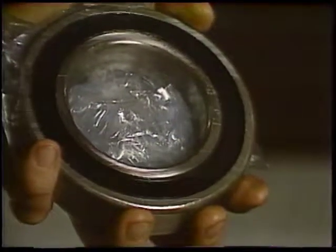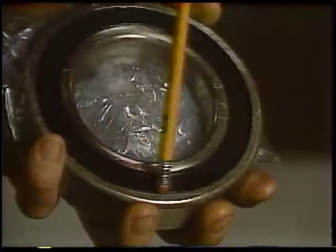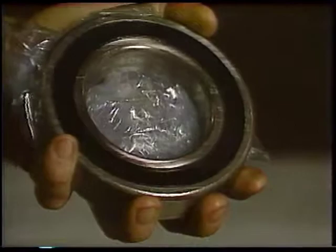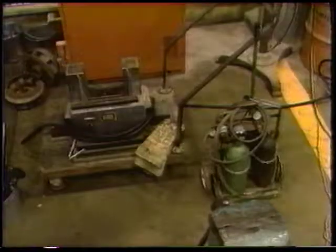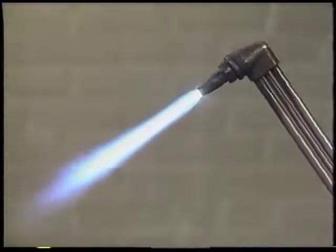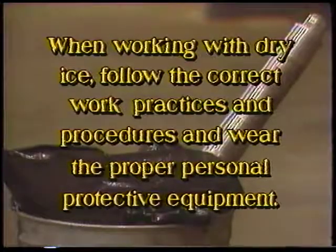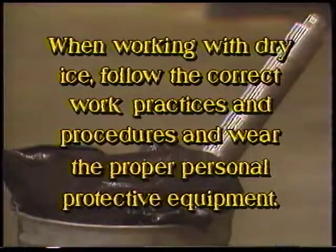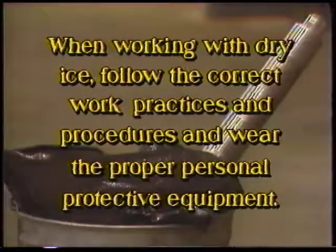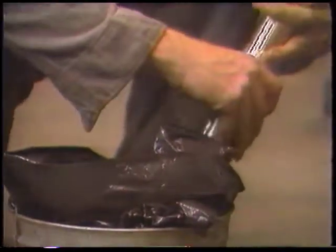If the bearing has rubber or plastic seals, take extra care not to damage them through overheating. If it is permanently lubricated with grease, you should check the manufacturer's specifications. Never use a welding torch to heat a bearing. The concentrated heat can crack or warp the bearing, and it may permanently soften the metal. If heating the bearing is not sufficient, it may be necessary to shrink the shaft with dry ice. Remember to wear the proper personal protective equipment and make sure you follow the proper safety precautions. If you use regular ice, it's important to protect the shaft with a plastic covering to prevent corrosion.